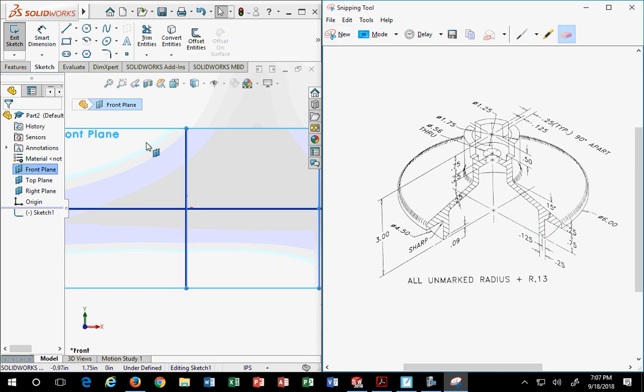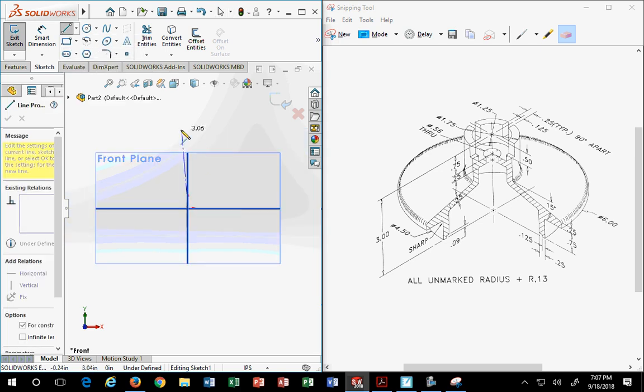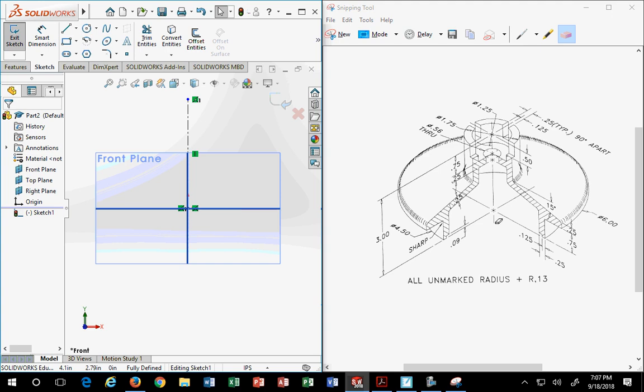So when you're over on this side, the first thing I recommend is to throw in a center line. Your center lines should be through the center of your axis. That is going to be the center of this, just like it has a center line. If you look over here, it has a center line right there. See that? That's that center. Everything is dimensioned off the center.